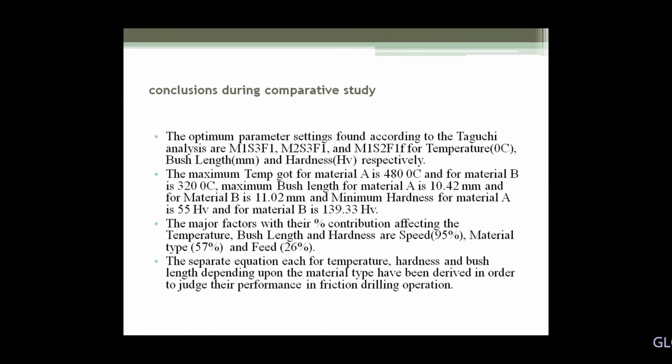We have calculated that, and the percentage effect on hardness is not very large, but a slight variation in hardness is found depending upon the material, sir. And the surface finish is quite good compared to twist drilling. We observed that, and with the help of the CMM, we checked the surface finish for some of the materials.